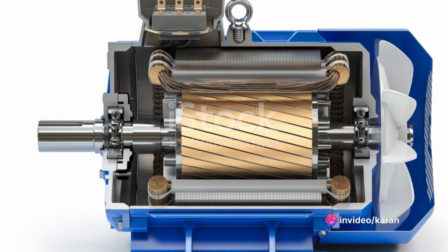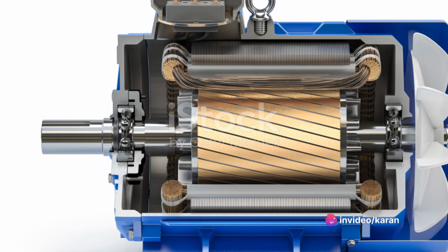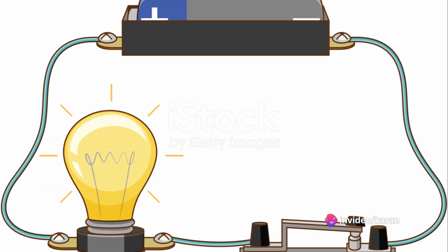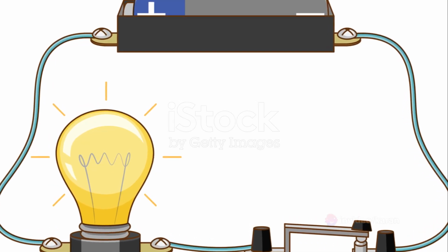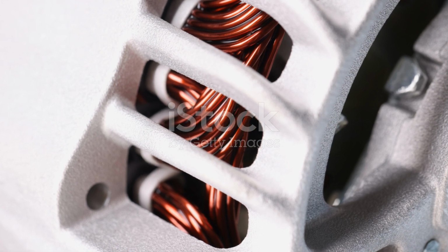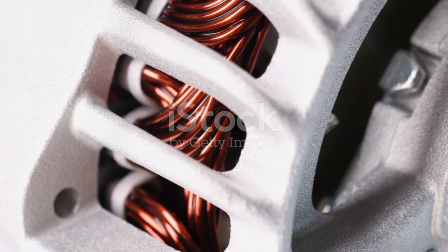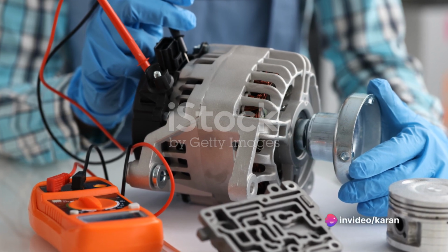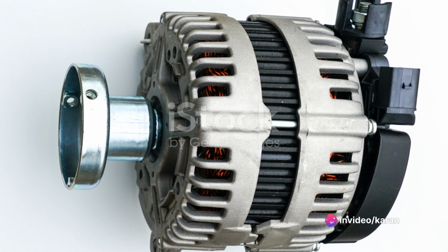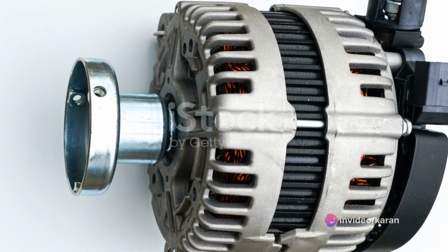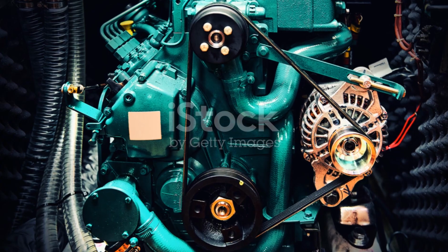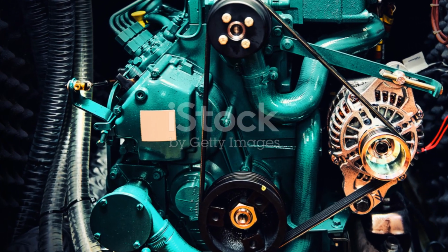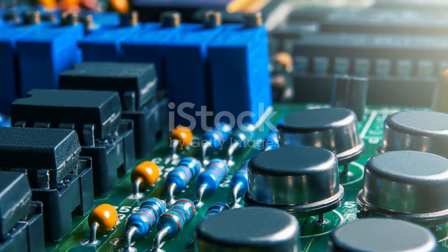First, let's talk about inductive loads, which include devices like motors. These loads have a unique characteristic. They have a lagging power factor. But why is this? Well, these loads require something called reactive power to function. This is the power used to maintain magnetic fields within the device. When an inductive load is operating, it tends to draw more current, resulting in a lower power factor.